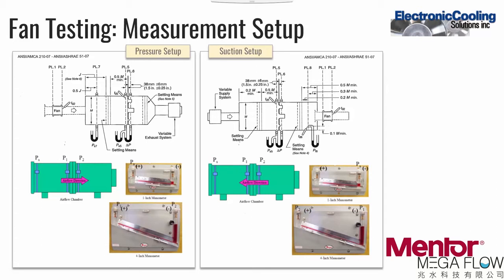For the other end of the PQ curve, which is the stagnation pressure condition with zero airflow, without changing the speed of the fan, the nozzle plates are closed completely so that no airflow goes across the nozzle plate. We have found that this is the most reliable way to create a zero flow across the nozzle plate. At this condition, it is important to make sure there are no leaks in the system.